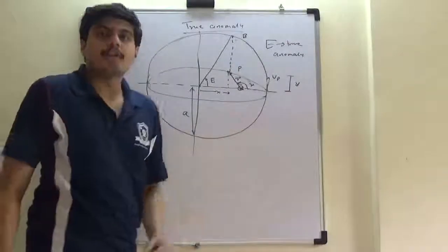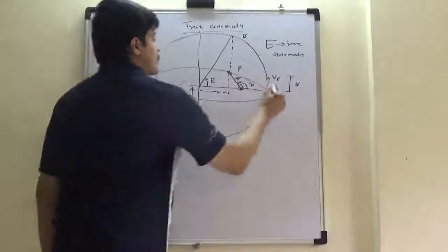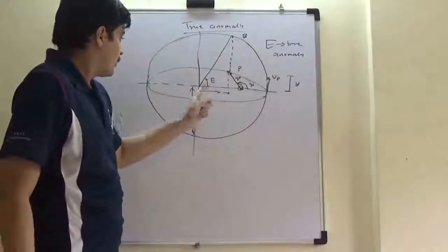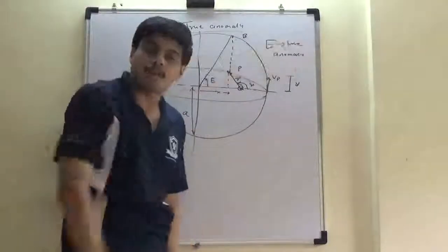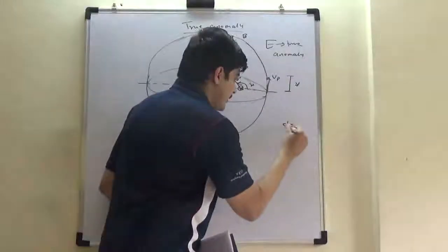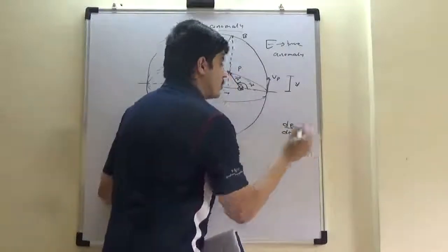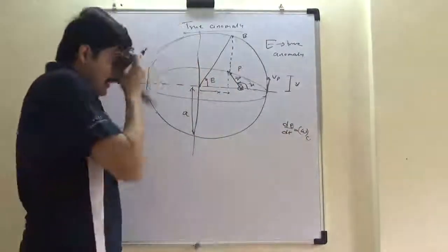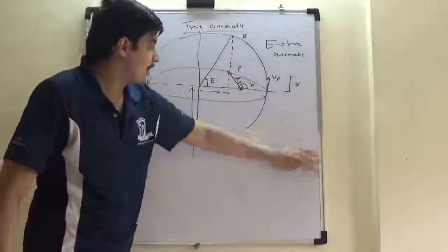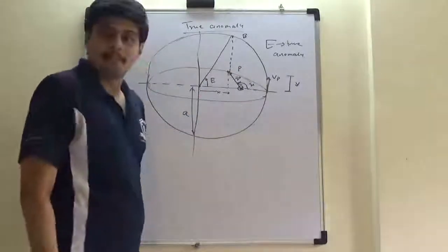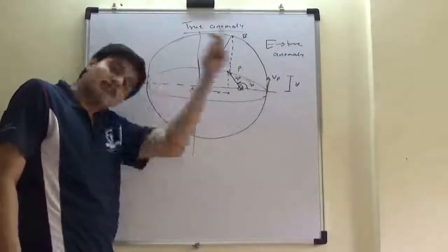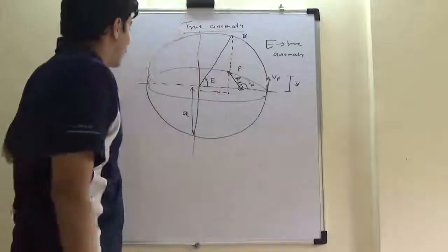Transforming an elliptical orbit into a circular orbit is of extreme importance, because things in terms of velocity and angle come true. Now omega of this hypothetical circular orbit gives me the instantaneous anomaly at any point, or dE by dt directly becomes omega of the circular orbit. So indirectly I want to transform my elliptical orbit into an equivalent circular orbit, so that these relations in anomaly are simple. The true anomaly is tan inverse of (1 plus e cos theta) by (e sin theta), very difficult and continuously changing. Here it is a constant tau.